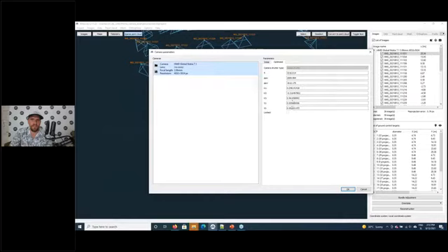And here we also have the other parameters. So the T1 and T2 are considerably lower than, for example, the radial distortion parameters. And PPX, so that's principal point X and principal point Y, they are at approximately half of the image size. So this all looks good.